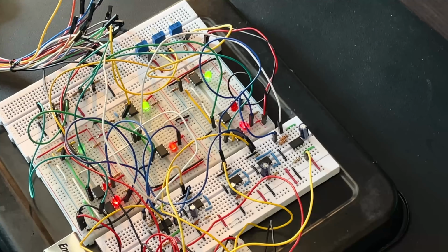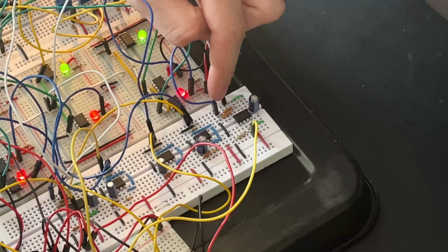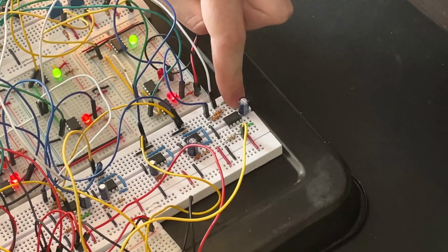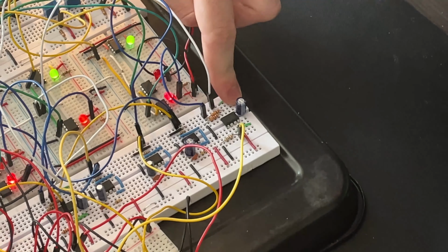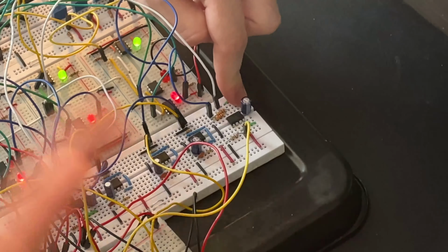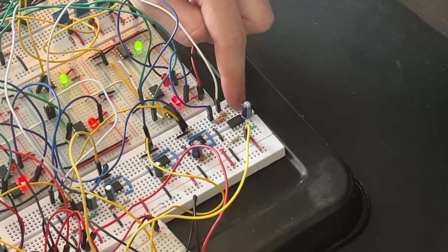So if we follow these blue wires, this first one is going to this integrator. The purpose of this is to delay changes in the output. If we were to have the voltage suddenly drop because we finally reached above the minimum, but then suddenly we went back down, we wouldn't want our outputs to suddenly turn off. So the point of this is just to smooth out the output.